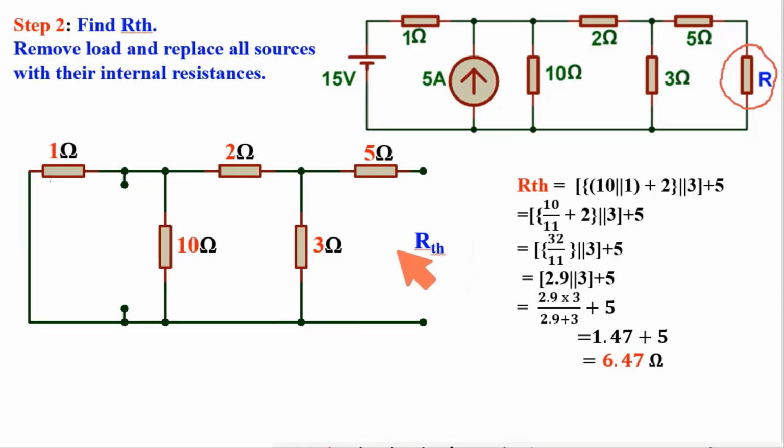If it is difficult to understand which resistance is in series or which is in parallel, then we can redraw this combination of resistances in a simpler way. Say I start from this point A, and say this is B. From A I walk first through the 5 ohm resistance. From this 5 ohm resistance I got two paths. One path is having 2 ohm, another path is having 3 ohm.